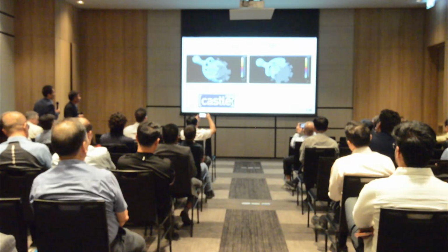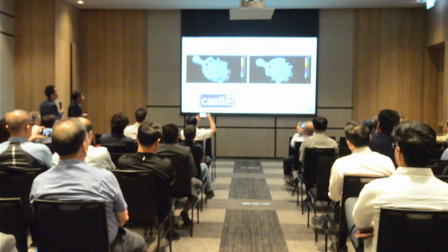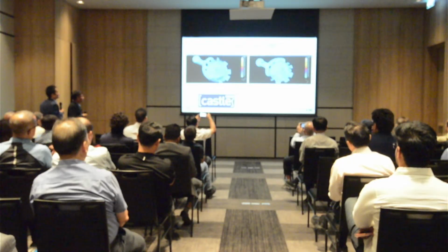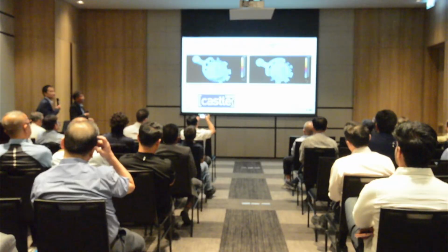This is where you use Magma, and we say this is the feeding behavior. The feeding direction is similar to liquid during feeding, but the viscosity definition is different. That's why later we will apply the Castle software for semi-solid simulation, using a commercial semi-solid model.